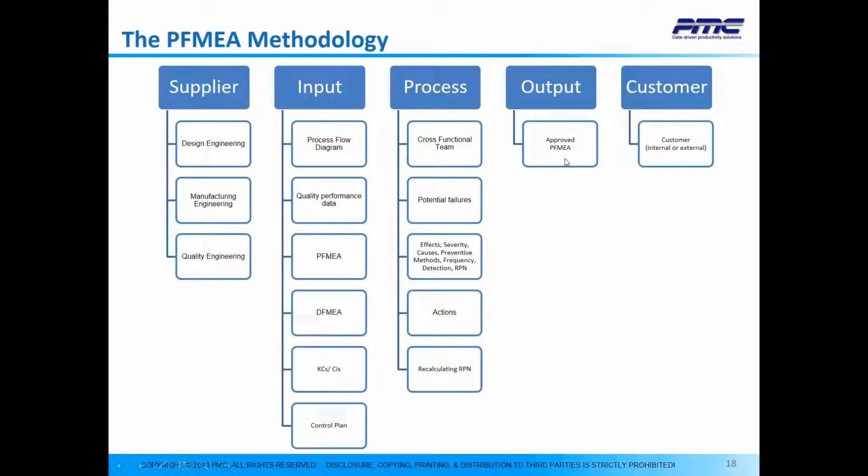Again, that PFMEA is developed by the internal team, and it's usually, if it's required, there are cases where it's not approved by the customer. Sometimes some customers may say, okay, just provide me the evidence that you did the risk assessment, and share it with me or review your PFMEA with me, but they don't have to approve it. They just review it and give an okay. But some customers, they have to. There is an approval process where they review it and make sure that they sign off on it before you can even move to the next step. And then finally, the customer, right? It depends on if it's an internal or external customer.